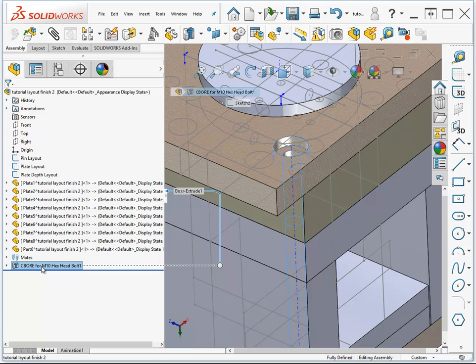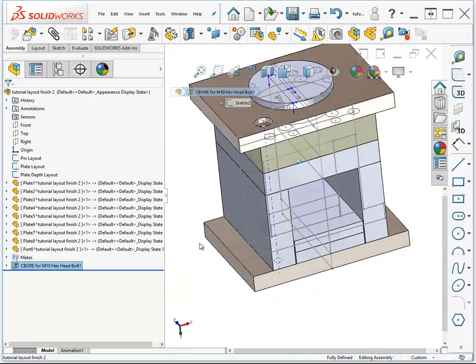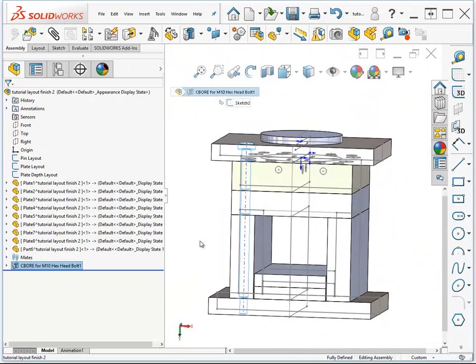You just really need to be careful about using any type of assembly features, especially if you're going to make reference to those assembly features with something that comes later. You're better off, again, having a layout sketch that drives the location of the holes and the hardware. I don't mean to scare you going into this chapter, but these are just some of the things that you need to know before you get too excited about all of this great functionality.